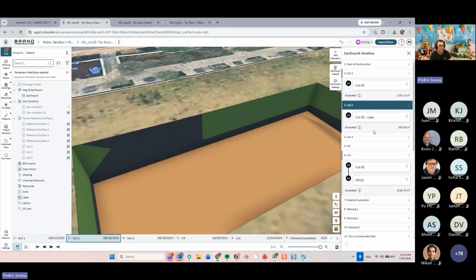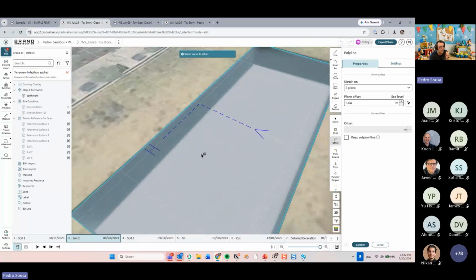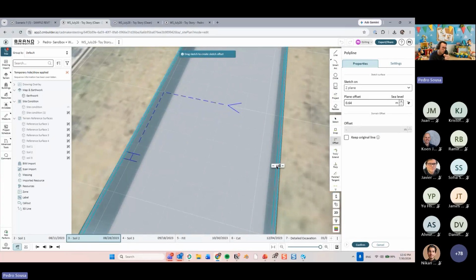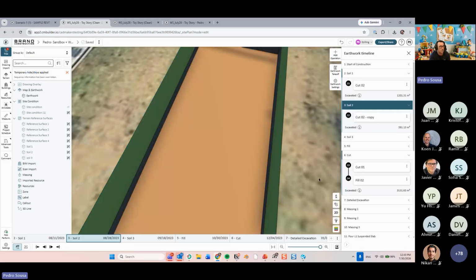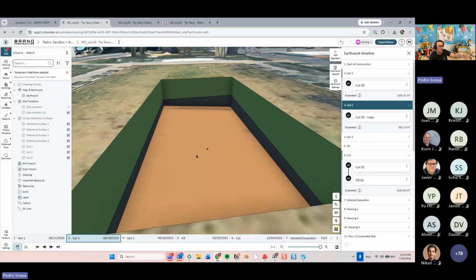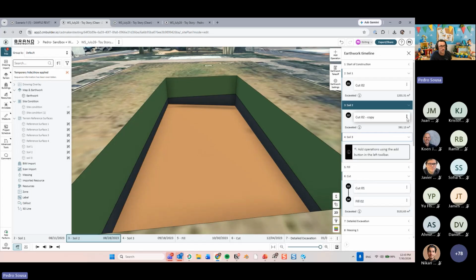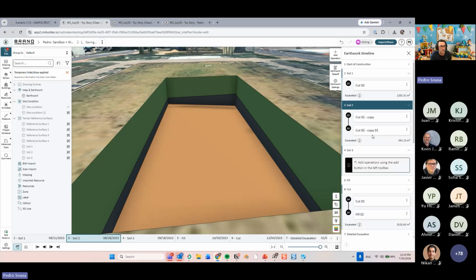So what we're going to do is bring this second cut a little bit towards the interior of the cut. I'm going to make an offset of 1 centimeter inwards, so those 2 cuts are not sharing the same surface. And then I have that coloring part over there going on. And then same idea on the next one.